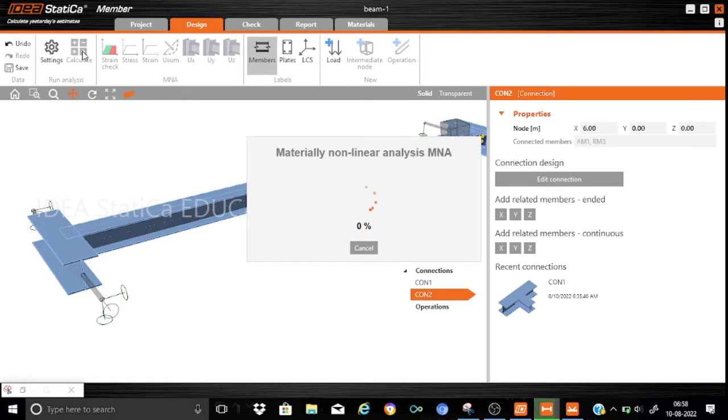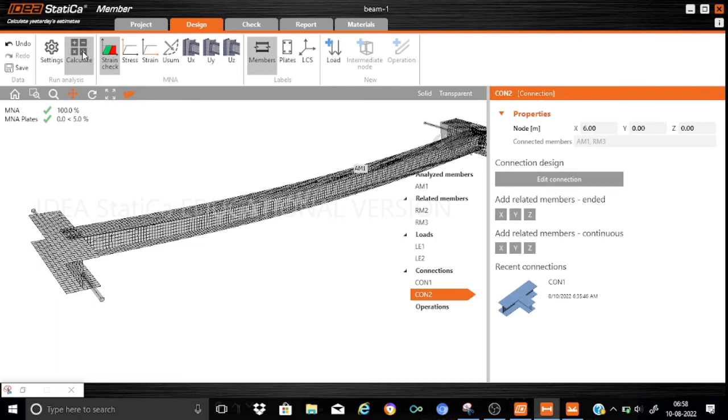So let us see. As you can see, the analysis will take say 5 to 10 seconds. What is very important is that I want to provide a small piece of advice to my engineers: you must be able to verify all the calculations provided by IDEA StatiCa through your simple hand calculations. That's very important, because getting a solution from a computer does not provide any guarantee that it is correct. You might have committed minor mistakes in the input of the geometry or the loads. You must be able to tell your client with confidence, yes, the analysis results are acceptable to me.